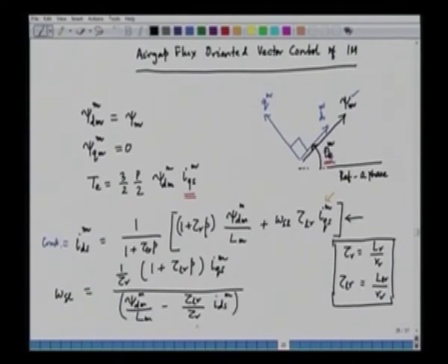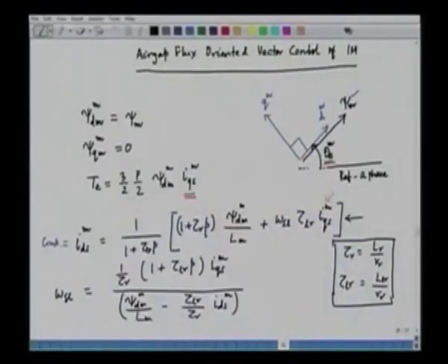So, usually when we want to transform the dq variables into ABC variables, in this case the variables are in the air gap flux reference frame, we have to use the angle of transformation. We have to transform the variables in the dq frame into the actual variables in the ABC frame, and in this case the transformation angle is theta em, that we have already discussed.